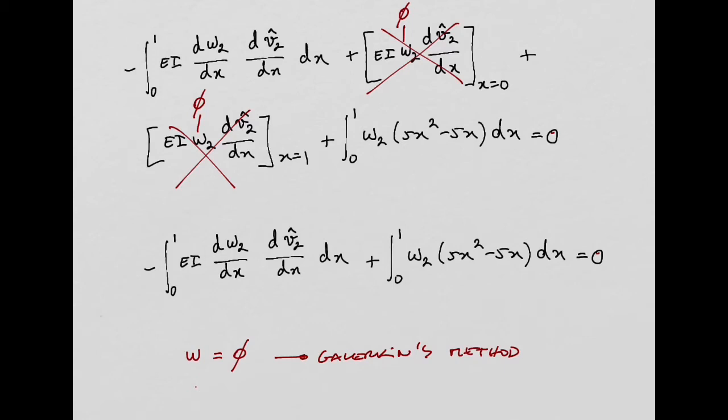And that is one important aspect, which is related with the selection of the shape functions for the problem. Like I said in the last session, we have chosen the shape functions so that they fulfill completely the boundary conditions, which was deflection for x equal to 0 and x equal to 1, the deflection at those 2 points equal to 0, right?